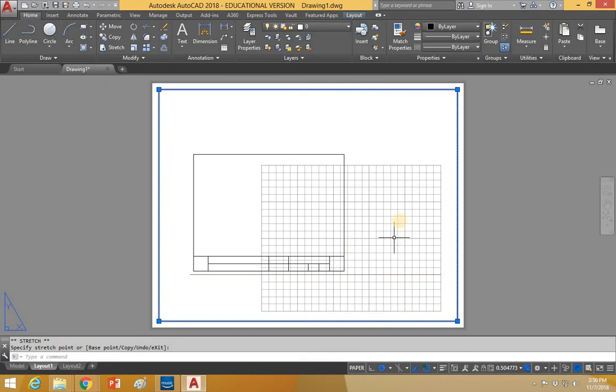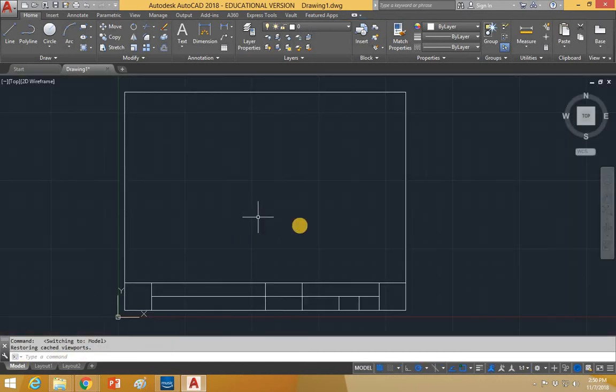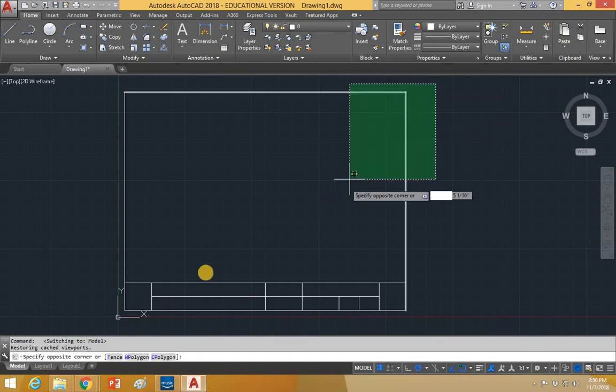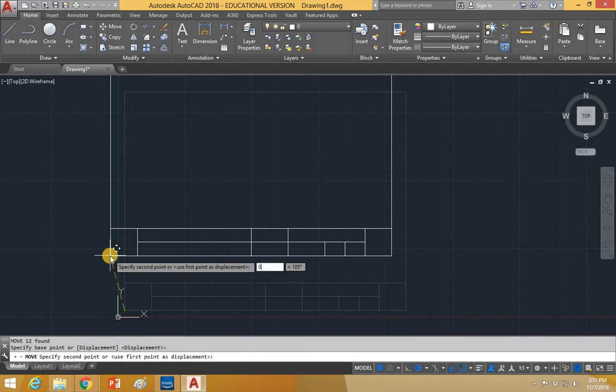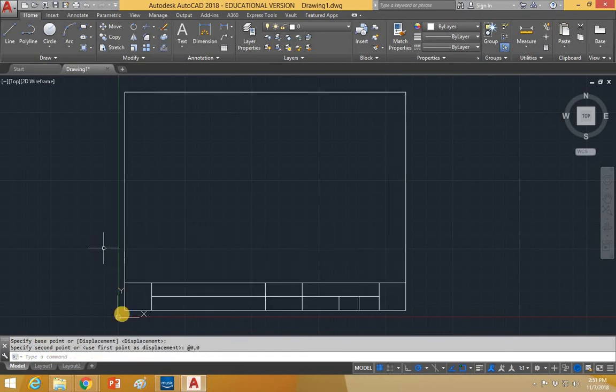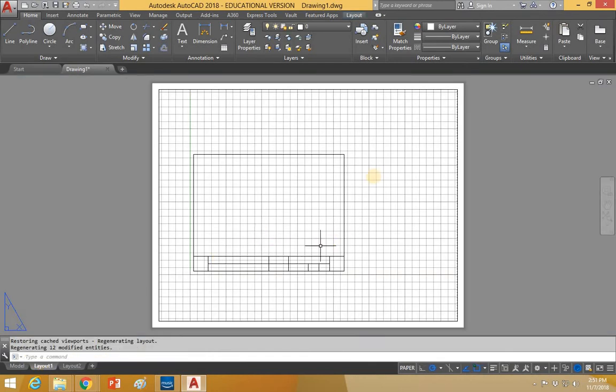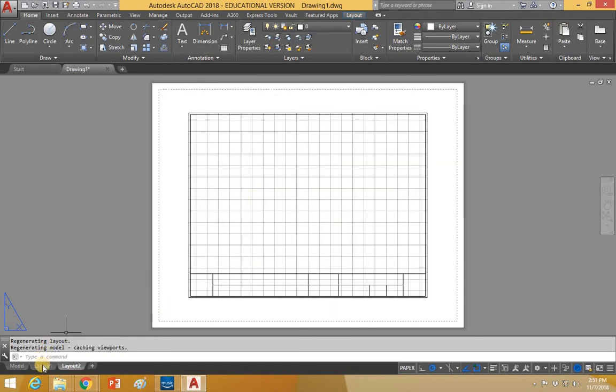Also, if you look at drawing limits, here's my limits. I don't know why I'm not sitting at 0,0 like I should be. It's not the most important thing in the whole world, but let's see if I can get myself there. If I select my object and then hit M-Enter for move, it's going to ask me to choose a base point, so I'm going to choose one. And now I'm going to say 0,0. Let's see if it goes where I need it to go. I made my thing bigger. I don't necessarily know why, but that's okay.